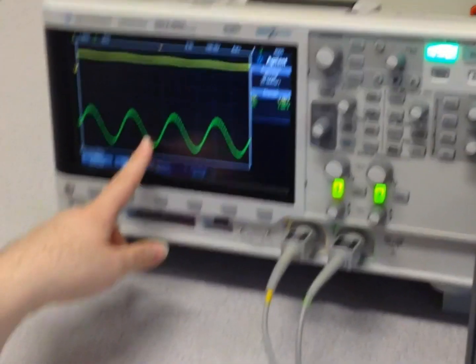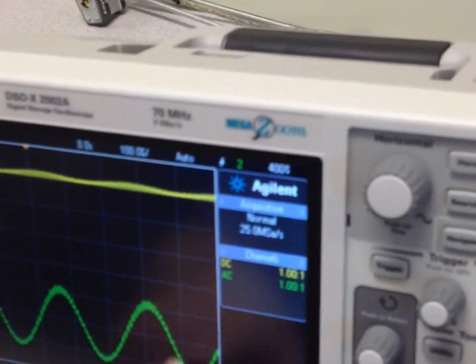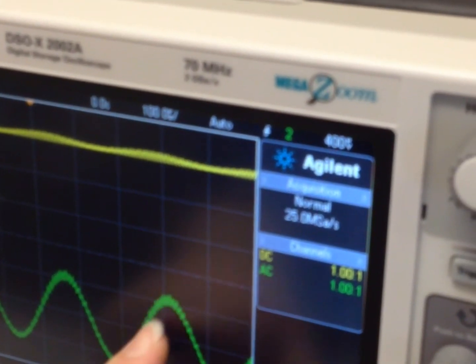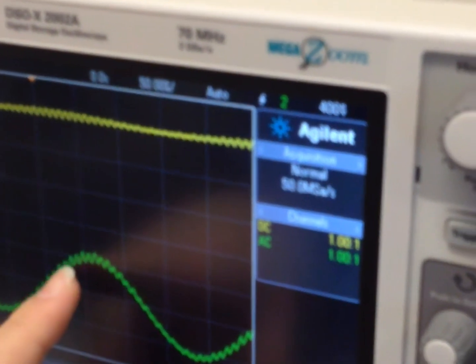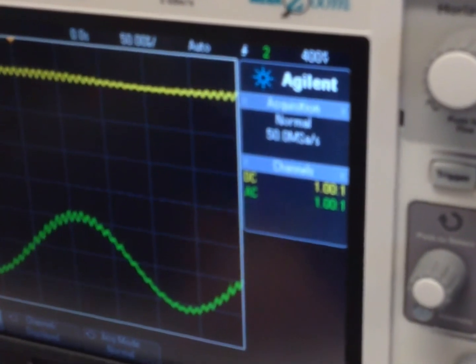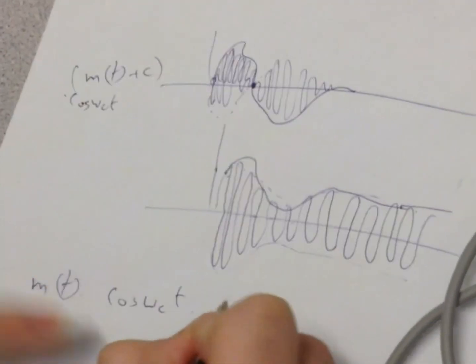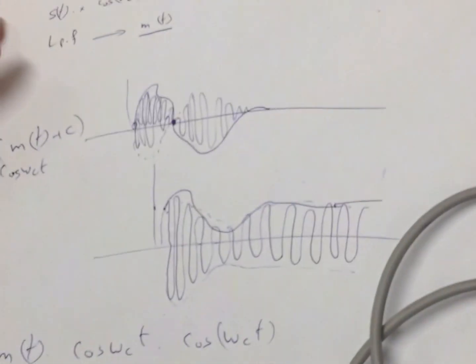This is TP4. We have our sine wave, as we see. It is good, but with very sharp edges, right? Many sharp edges. Why are there sharp edges? This is before the filtering, right? So we have our m of t multiplied by cosine omega ct. This is for the transmitter, and in the receiver it is multiplied again by cosine omega ct.